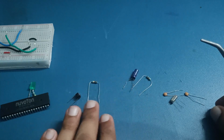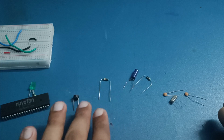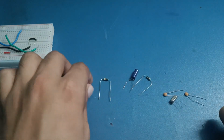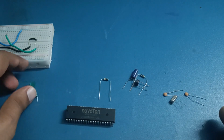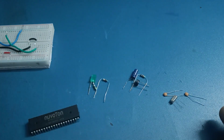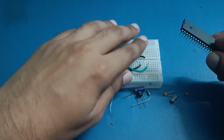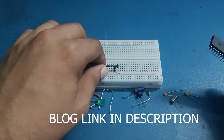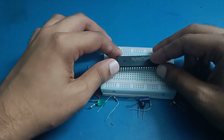This is for the reset circuit. This resistor is to make the external access pin high. This is the reset switch, which goes with the reset circuitry. And this is the LED that we are going to interface. So let's make the connections. The circuit diagram is given in the blog, and the link is in the description. I will make the connections and come back.